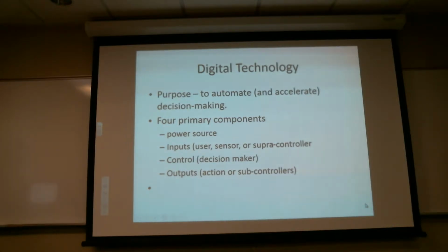So okay, we're going to hit the starter, start spinning things up, and at a certain value of both RPM and pressure ratios, we say, all right, kick the igniters on. Okay, the igniters are working, got the appropriate amount of current coming through the igniter. So then I'm going to kick the fuel on. Okay, fuel's been on for X amount of time, I should see XYZ temperature rise. I'm getting the temperature rise, it's not going too high. Continue the start cycle, and on and on and on, and take it all the way through to the point that it's done with its little scenario, and says, okay, there you are at ground idle, ain't it grand?